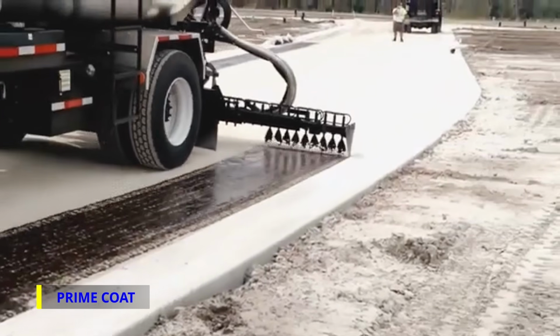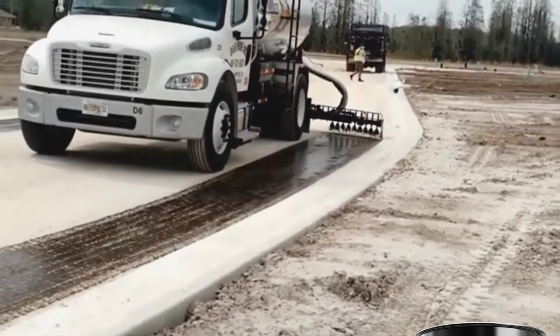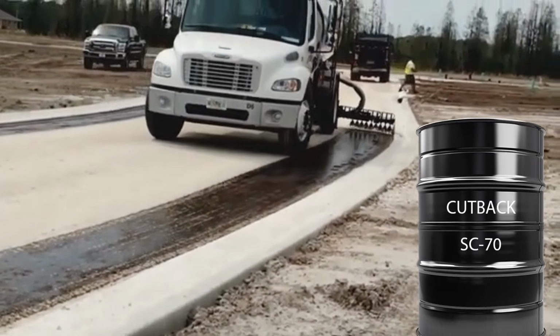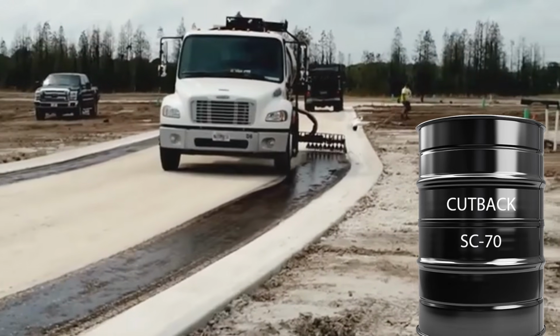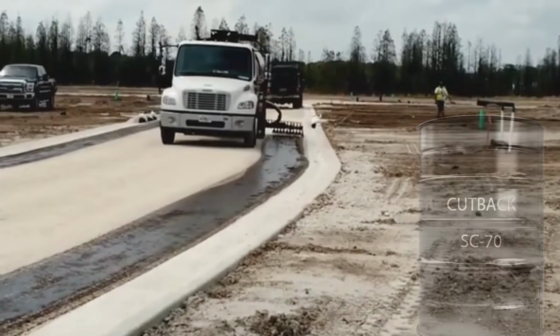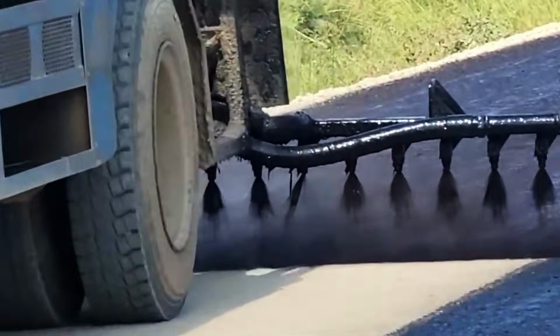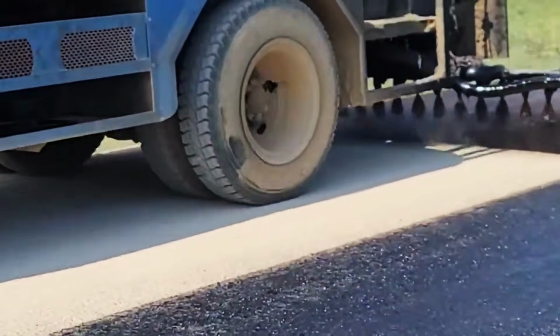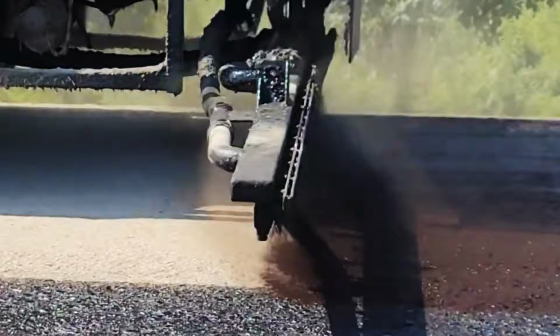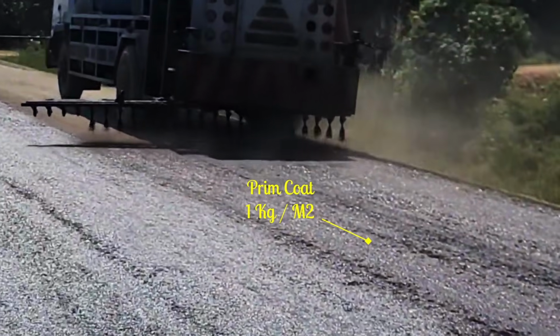The prime coat. The prime coat is the binding layer between bituminous and non-bituminous surfaces, such as wet mix macadam. Cutback bitumen grade 70 is used as a prime coat. The material shall be heated to a temperature of around 150 to 160 degrees Celsius, properly blended for 2 to 3 hours, and uniformly sprayed at approximately 1 kilogram per square meter over a dry and clean wet mix surface using a mechanical sprayer. Normally, it shall be allowed not less than 24 hours to penetrate into the wet mix before laying asphalt.